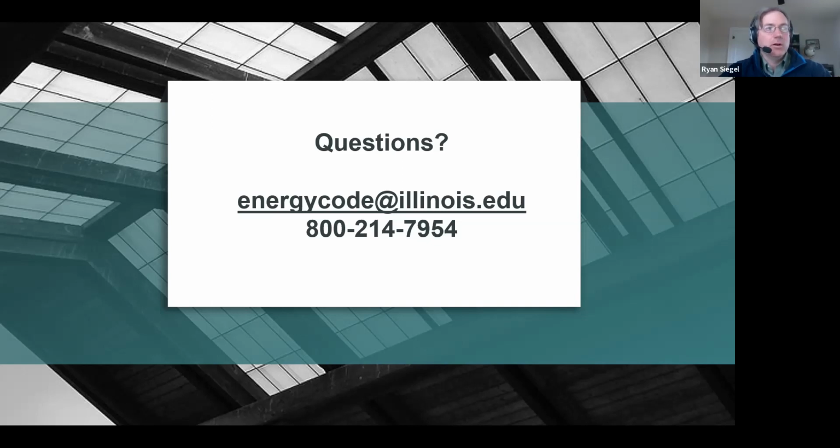Commercial will take a little bit longer, partially because you're dealing with much more volume. So it just takes a while longer to actually come up to the test pressure in order for the fans to move enough air for that. But yeah, residential, the actual test, a few minutes. For commercial, again, that's going to range depending on the size of the building, how long it takes to come up to pressure. It would not be uncommon for a commercial test on a large building to take upwards of a half hour, just to bring the whole building up to pressure and so forth.